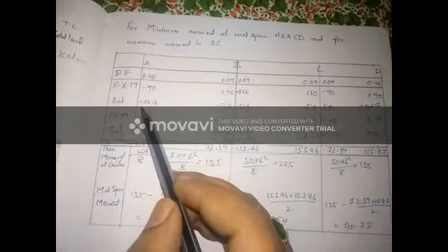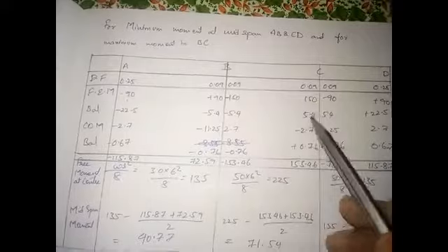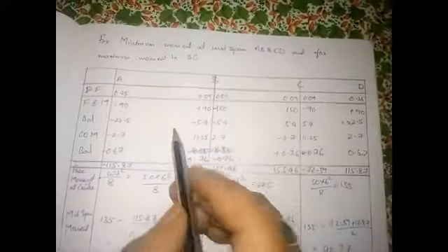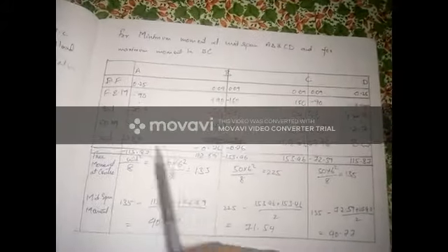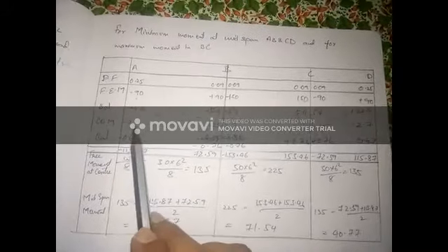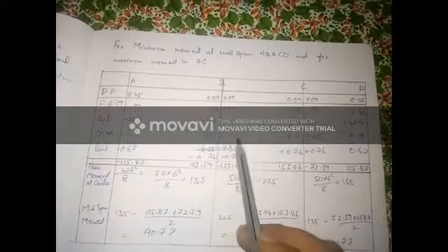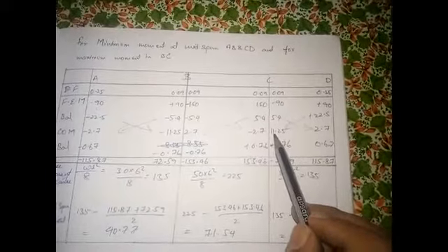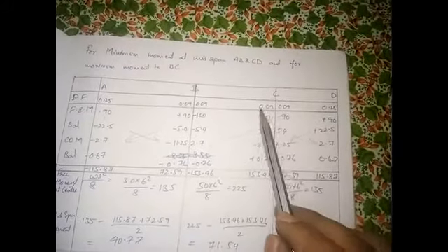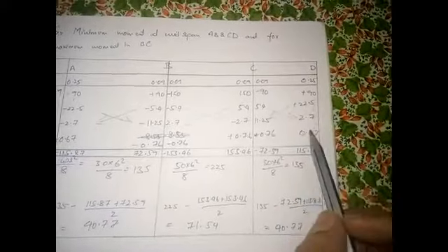Then the balancing we will be doing similarly, that is minus 22.5 minus 5.4 minus 5.4, same, and carryover, that is from this way, cross way. After this carryover, then balancing, which is minus 2.7 into 0.25, minus 11.25 plus 2.7 into 0.09, and next minus 2.7 plus 11.25 into 0.09 and 2.7 into 0.25.